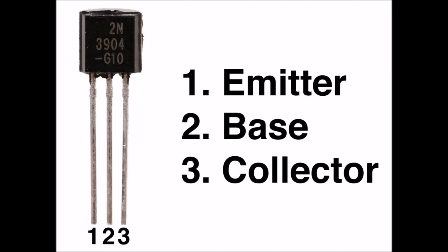Page 380 at the top. How alpha and beta relate. Whenever base current flows in a bipolar transistor, we can calculate the beta in terms of the alpha with the formula thus, and we can calculate the alpha in terms of the beta using the formula as seen. With a little bit of algebra, we can derive these formulas from the fact that at any instant in time, the collector current equals the emitter current minus the base current.